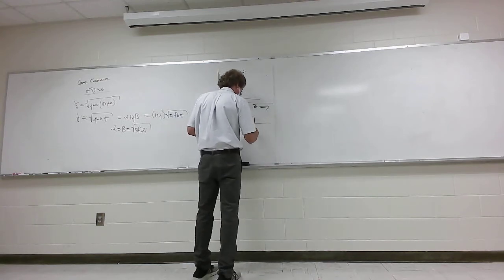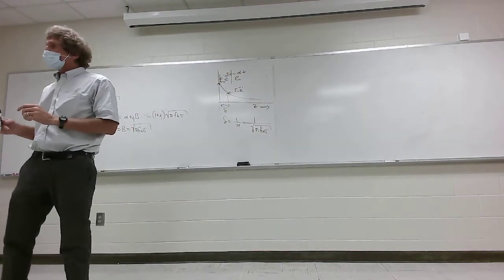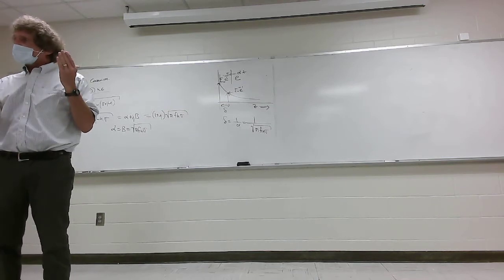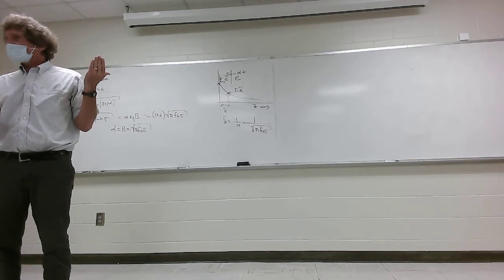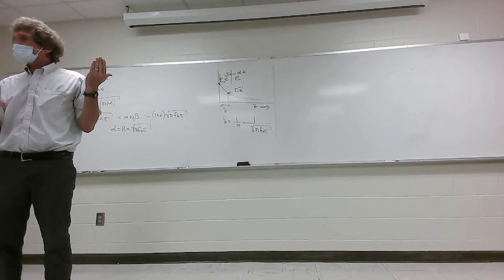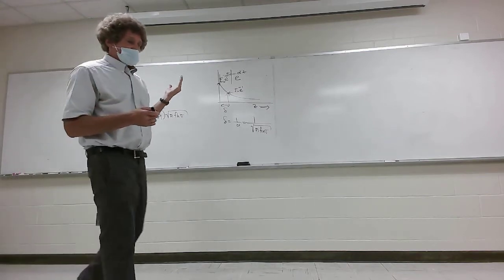It's 1 over the square root of pi f mu sigma. That is the skin depth. It becomes very important. It's the value that gives you an idea. About 33% of the field's value is left after that point. The waveform is down to about 33% of its original peak, all right? This is real important. So, how do we use it?